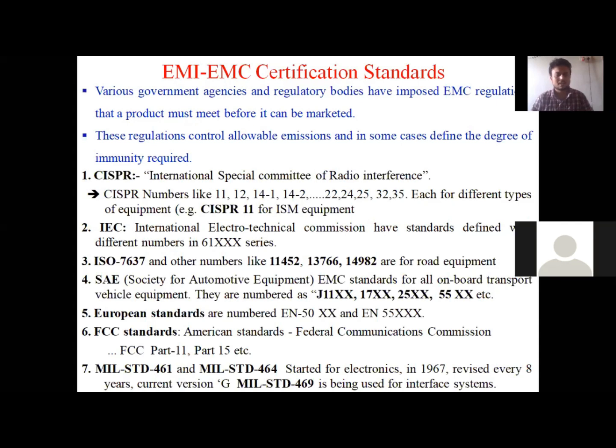What are those tests telling us? Those standards generally define some threshold values of parameters. The voltage or the EMI or any other parameter generated by that device should not exceed the threshold defined by those governing agencies or regulatory bodies. If it is exceeding those levels, you cannot launch your device for commercial application. So when you want to earn money by launching your device in commercial applications, your device must pass these tests. We'll talk about these tests a little later, because that is the end of the chapter.